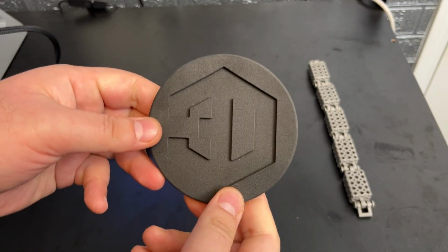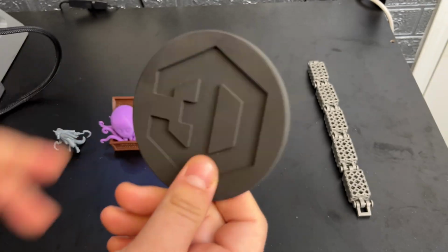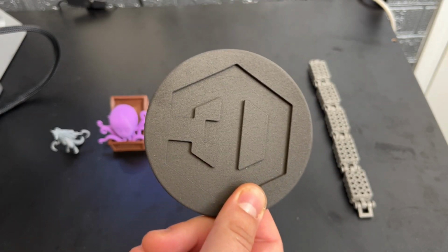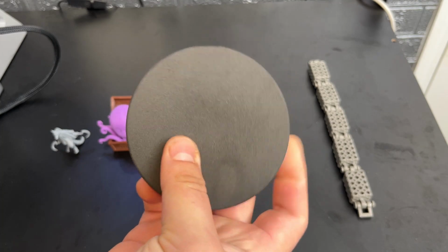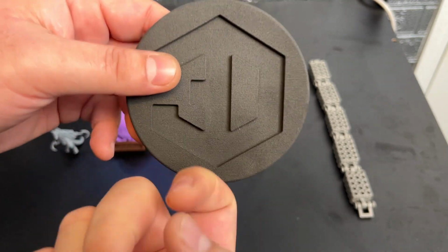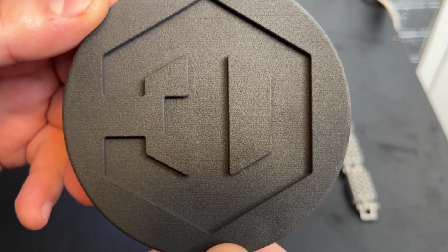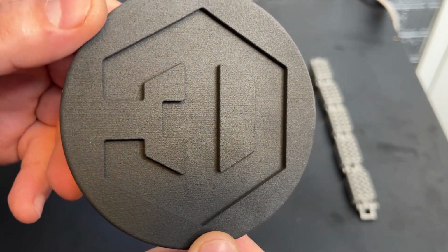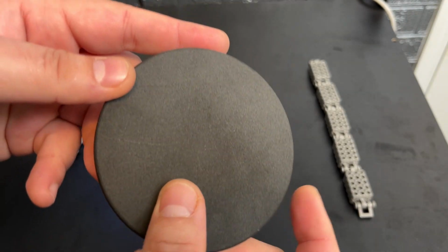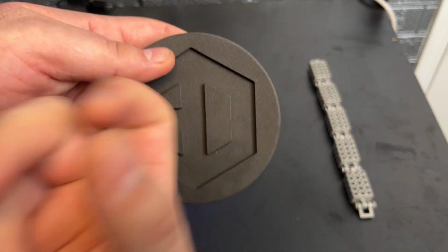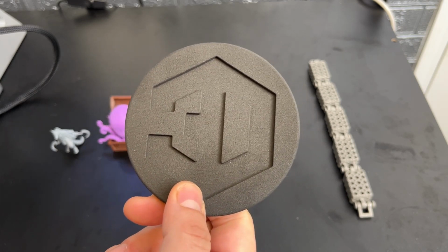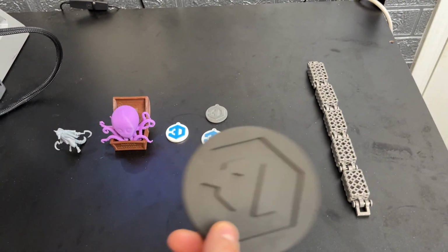And the next on our list is the SLS, and this stands for Selective Laser Sintering. And the common uses for this are functional parts, complex geometries, high temperature applications, and I really like the way this thing feels. Let's get in there for some details. Looks like there is some light layer lines going on, and like the MJF, this has a little bit of a grainy texture, but it's still very smooth. This is the fifth on the strength hierarchy, meaning it's getting stronger and stronger as we go down the line here.